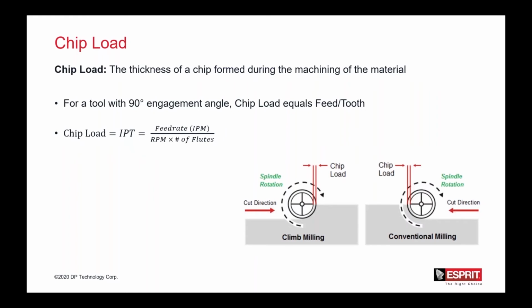And this is an example of the chip load. Chip load is used to determine the optimal feed per tooth for the cutting cycle. Recommended feed rates from cutting tool manufacturers are generally measured at 50% step over. During profit milling, we typically don't have a very high step over. Once you define your engagement angle, the step over is pretty low, and that again is what will reduce that tool load and also reduce the chip load. And there's a calculation there for how that chip load is calculated. Formula there for you.